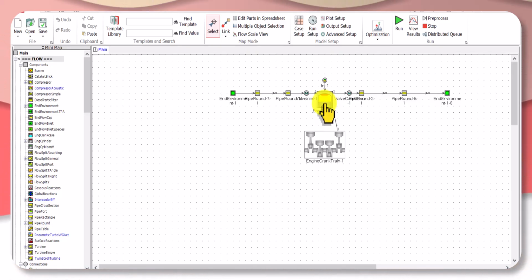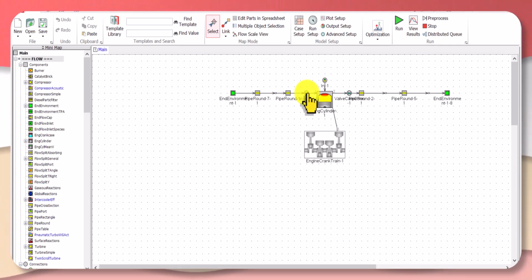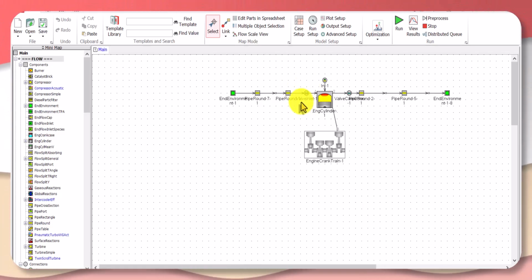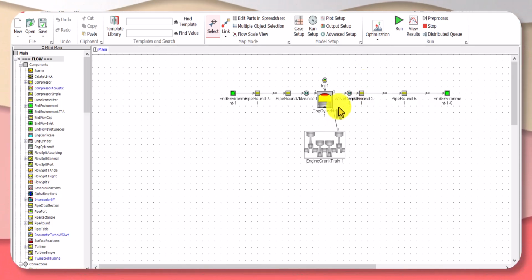And absolutely in this video we have the valve system. Actually, valves are responsible for opening and closing the intake and exhaust passages of the cylinders. At the right side of the cylinder here we have the intake valve, and on the left side we have the exhaust valve.